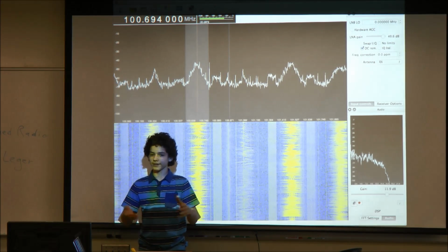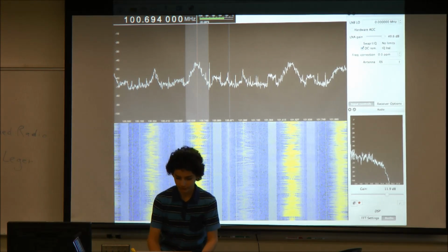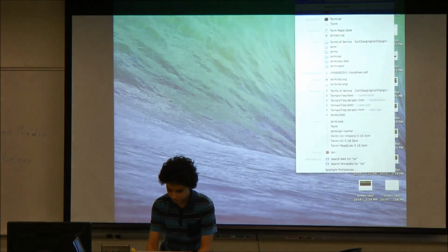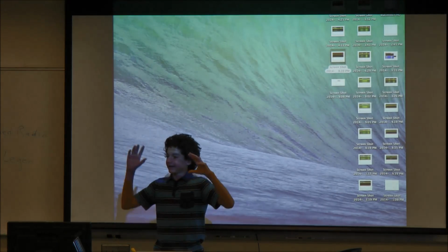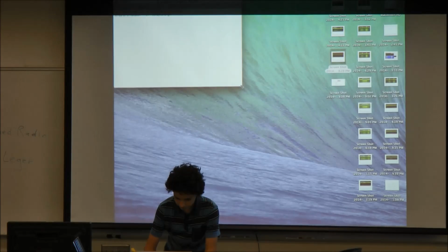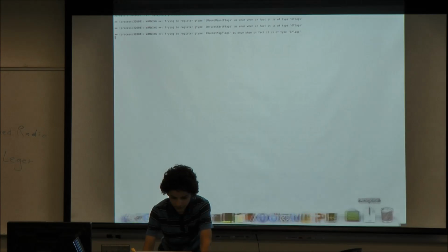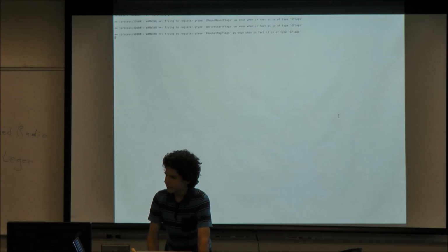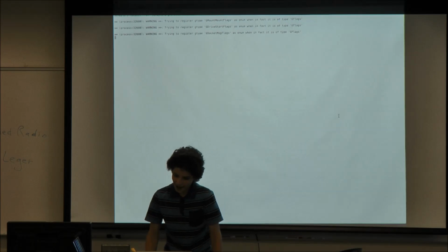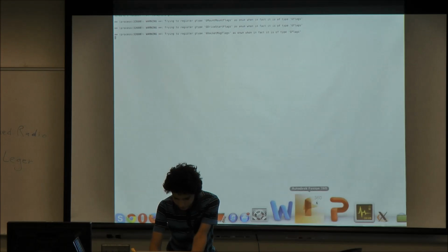Another thing is, are you familiar with those traffic receiver things that will say the current traffic is whatever, and they don't cost anything, or it's for life? Some of those actually use the data encoded with the radio data system to get that, because some stations will encode traffic information. So you open up a terminal, we'll just start GNU Radio, and that's GNU Radio Companion, and it will open. You need Xquartz installed if you're doing it on a Mac, and GNU Radio should open.